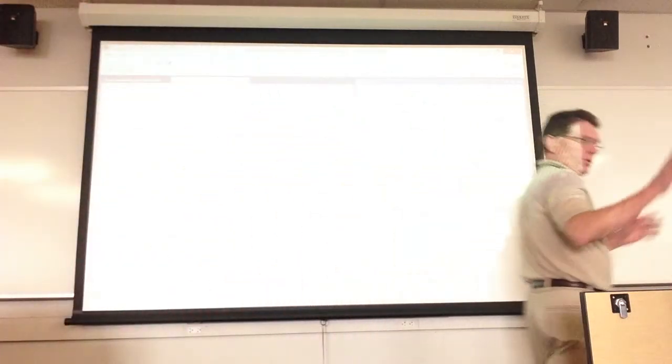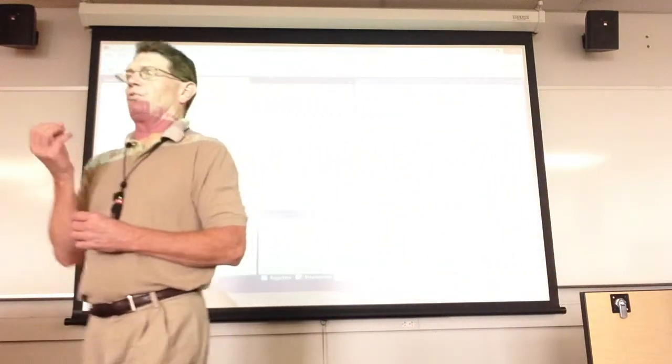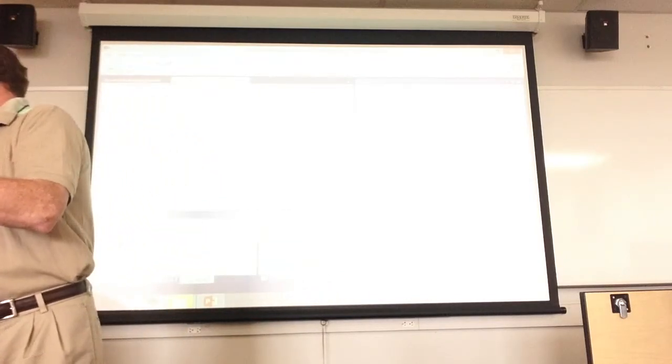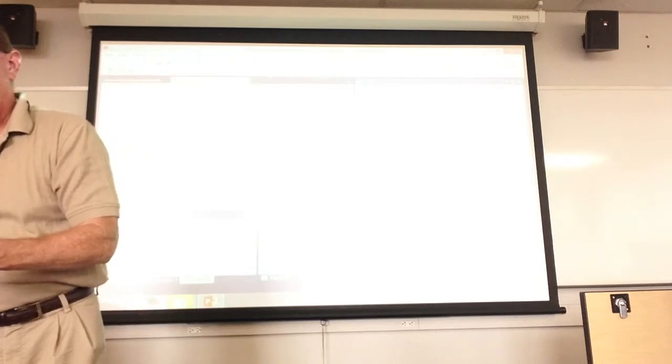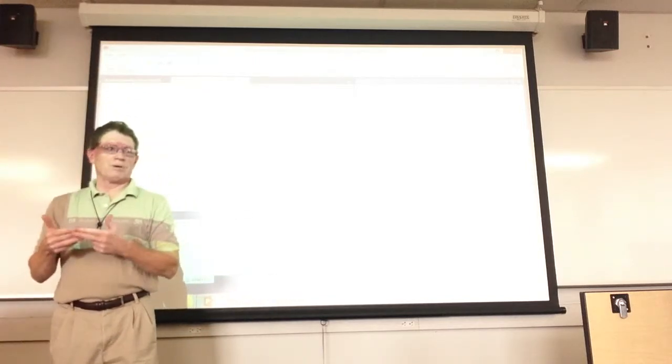All right, is everybody on the same page? Okay. And then we could just keep doing this over and over again. But I just wanted to show you how you can simulate, as you're going to be doing in lab this week, those I/O pins. If you're going to simulate a read in from an I/O port, you first have to set it up to be an output port, then you have to write to it, and then you set it up as an input, and then you read from it. You get my drift?